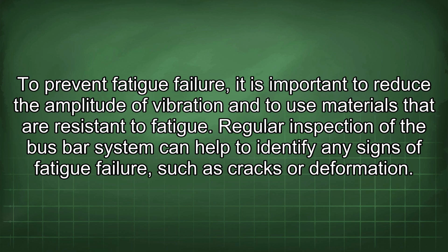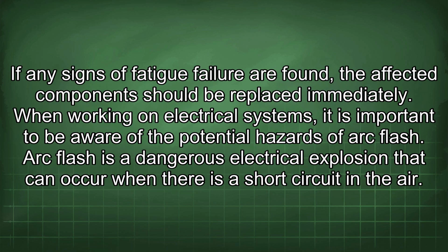To prevent fatigue failure, it is important to reduce the amplitude of vibration and to use materials that are resistant to fatigue. Regular inspection of the busbar system can help to identify any signs of fatigue failure, such as cracks or deformation. If any signs of fatigue failure are found, the affected component should be replaced immediately.